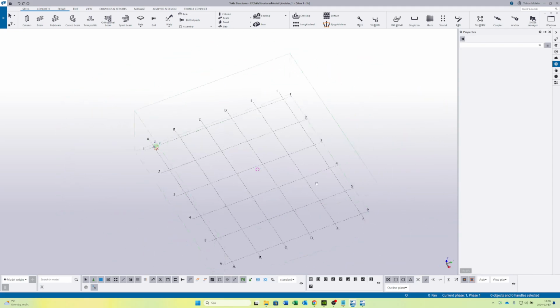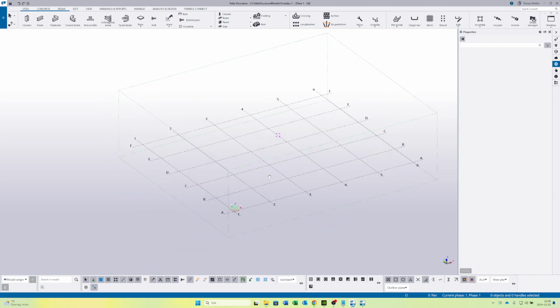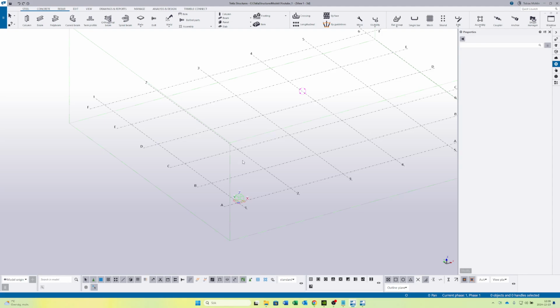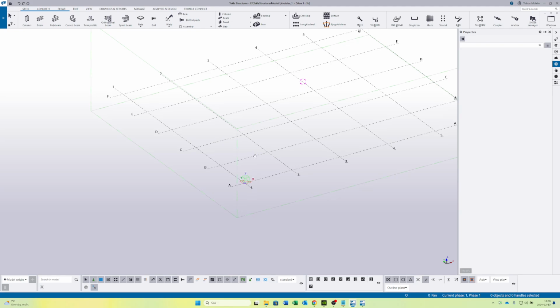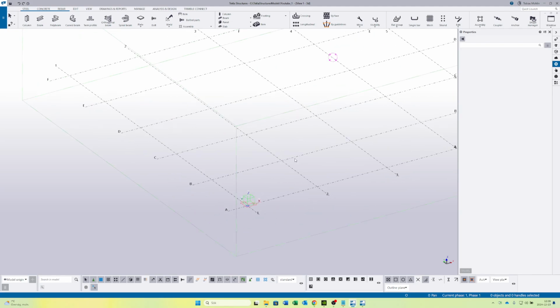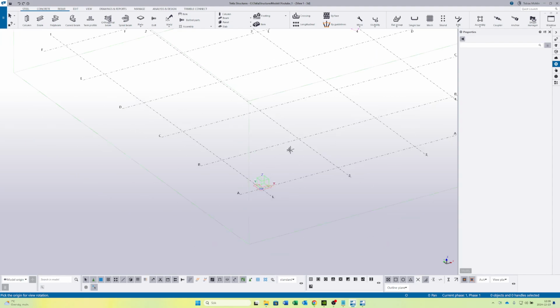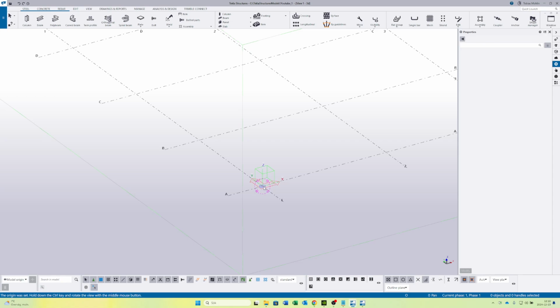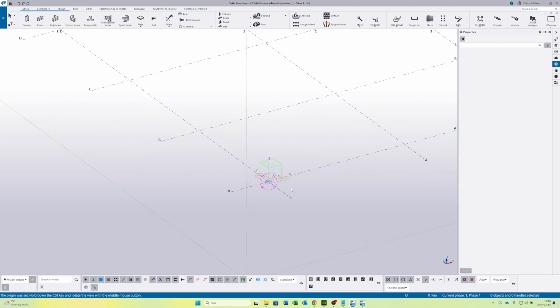And if I want to change that, I don't always want to rotate around the middle here. Maybe I have a column standing over here in the corner and I want to rotate around my column. Then I want to change this point to get over here instead. And I can do that by pressing the short command, which is V, just a simple V. And you can see now that I can place this somewhere. So let's place it here in the corner, and that means that I've changed my rotation around this point now.